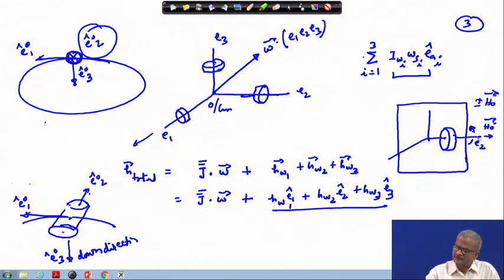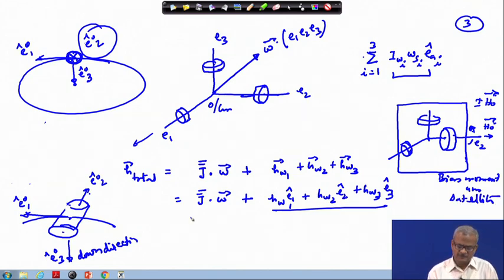And if it happens that other wheels are not rotating, but one wheel you have rotated for giving some bias momentum to the satellite, in that case we call this a bias momentum satellite. In this small figure I am not able to show it, but this is the whole purpose, that depending on the previous rotation direction we can have this H 0 either plus or minus.